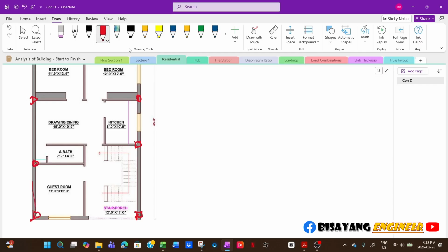So this is 45 feet. I would say this is around 25, or at least between 25 to 30 feet. I mean, you can design whatever span you want, but it will be really big. So if you want to minimize the size of your structural elements, then you have to add more columns and more beams. Now, this one here, if you notice, there is an opening here.